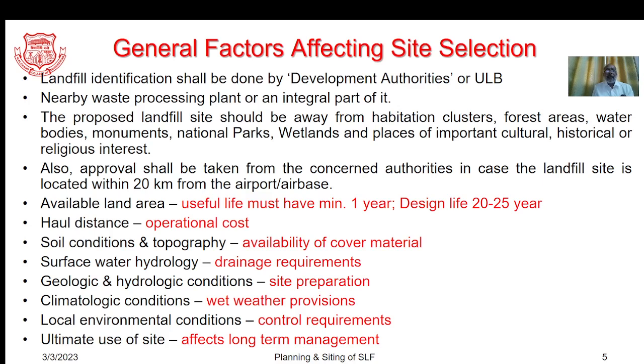But one must think that this kind of facility should be away from habitation clusters, forest areas, water bodies, monuments, national parks, wetlands, and certain places of important cultural, historical, and religious interest. Also, if such a facility is intended to be sited near an airport or airbase, and if that distance is within 20 kilometers, one has to obtain permission from the aviation authority.